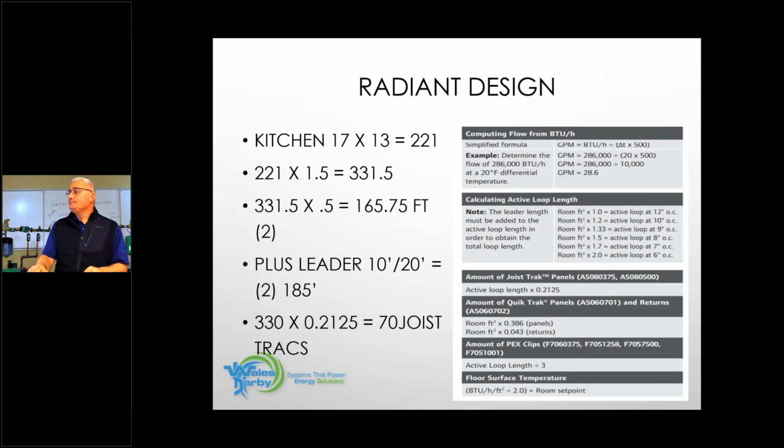Jim, while you're on that total lengths and everything, there was a question that came across asking about cabinets and islands and things. Yeah, so when we're under the floor, we do have to take into account cabinets and islands. If there was an island in the middle of that kitchen, we're not going to stop pulling the tubing down that bay. We're going to go underneath. So we do take that into account in our calculations. That will be unheatable space, and you guys would not put the plates under there. You'd stop the plates before, the tubing would continue on, and then we'd pick up doing plates after the fact. You'd run the tubing right to the end of the bay, so yeah, the tubing would be underneath the cabinets, all right?